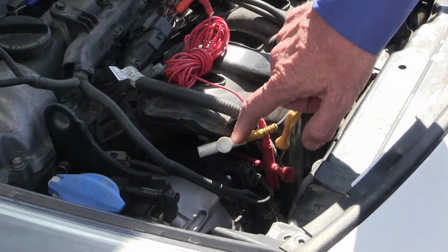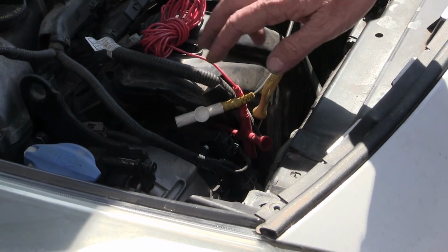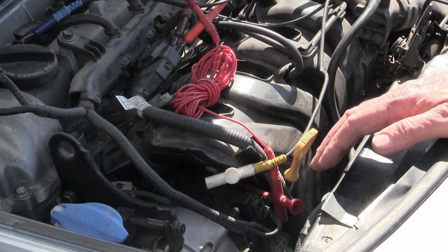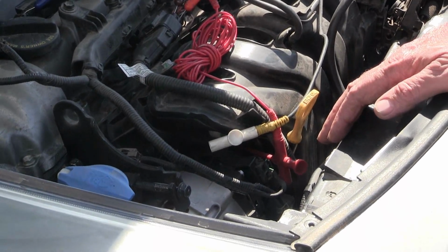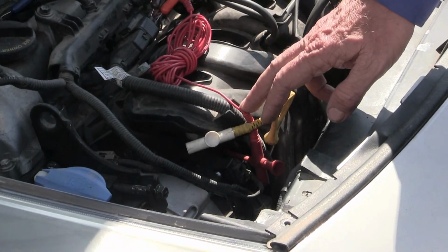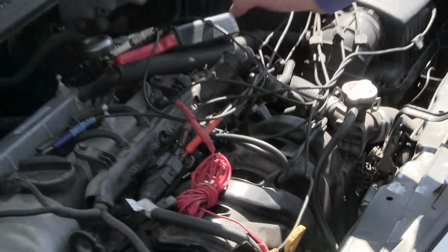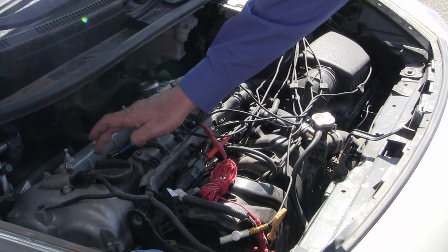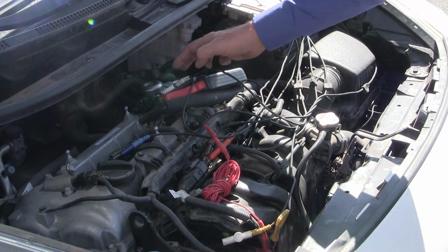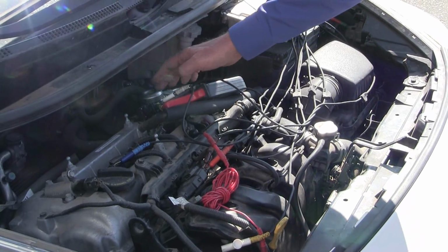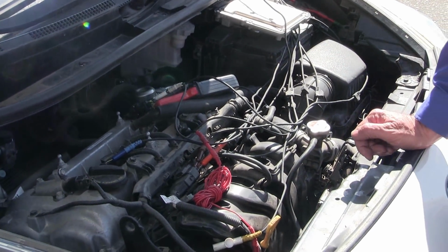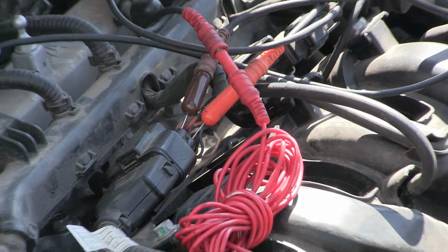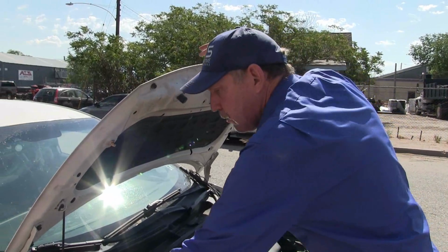I've got channel 1 in yellow on the high pressure rail sensor output. I've got channel 2 in red on the 5-volt input to the sensor. If I've got a low voltage code, I'm figuring either my output is bad or my 5-volt in is bad, so those are the two things I want to watch. Channel 3 green, I've got an amp clamp on the high pressure regulator. Channel 4 blue is on the number 1 ignition coil. Then I've got channel 5 white and channel 6 purple. Those are reading the voltage that controls the high pressure regulator. And then I've got channel 7 and 8, orange and brown. That's the number 1 fuel injector. Let's go ahead and get the data and go for a drive. Let's figure out what's wrong with this beast.